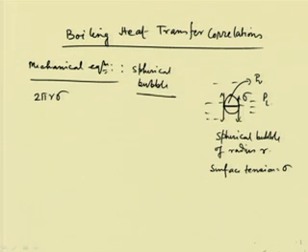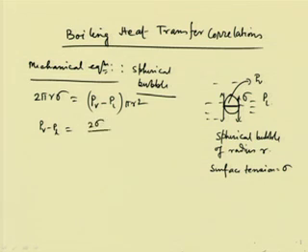Okay. That is assumed, and that is equal to P V minus P L, the pressure difference. We know that the pressure of the vapor is more than the pressure of the liquid, and this is multiplied by pi r square, the area on which the pressure acts. Therefore, we can say that P V minus P L, the differential pressure, is balanced by this term, 2 sigma by r.